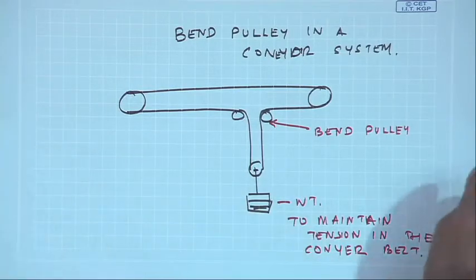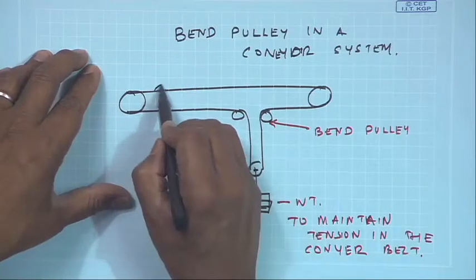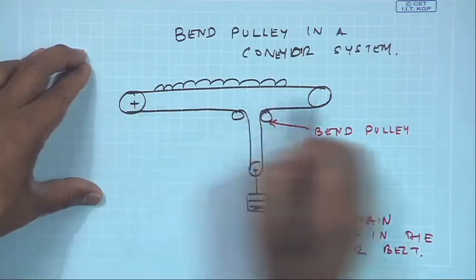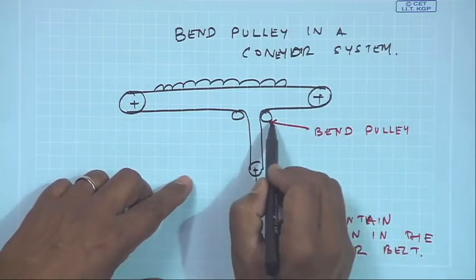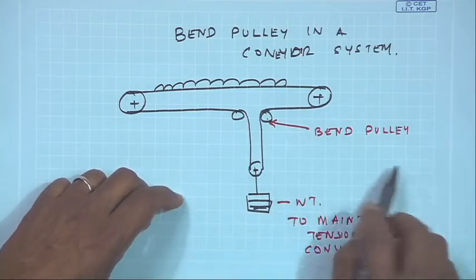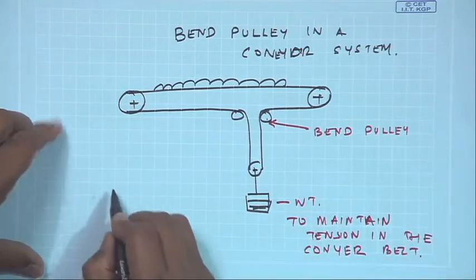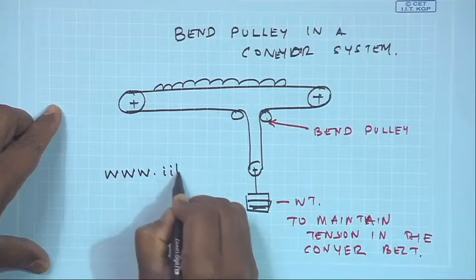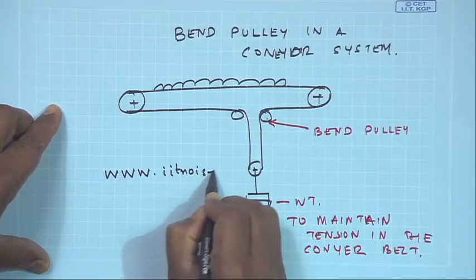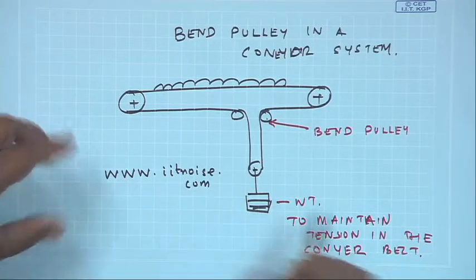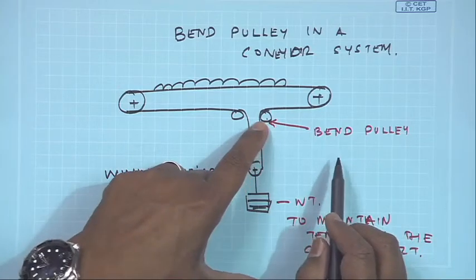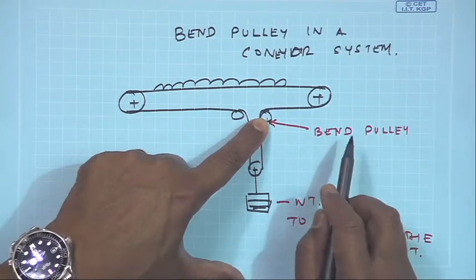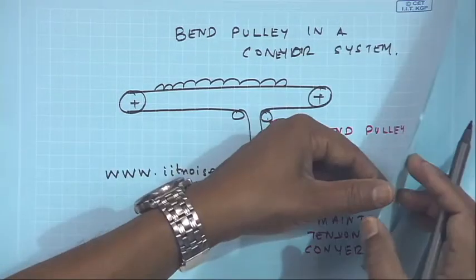Excuse my typos and spelling mistakes, that is because in the flow I want to rather concentrate on the topic here. So, this bend pulley failed, and you will see in my book the details, which you can find in the website. Okay. This failed, and we realized after doing a failure analysis, it was improper heat treatment done after welding of the pulley.